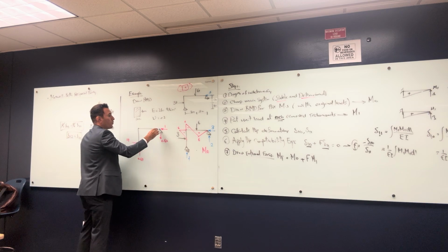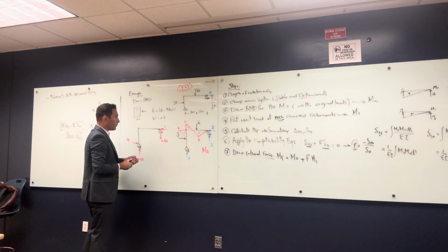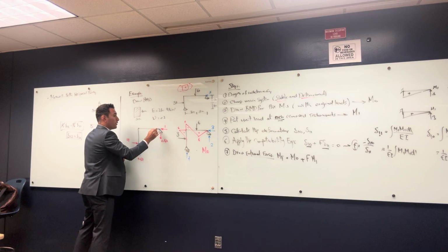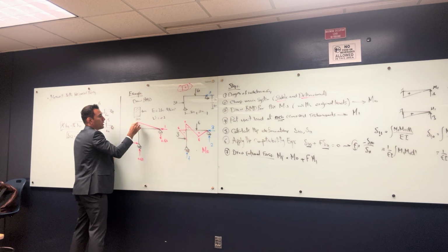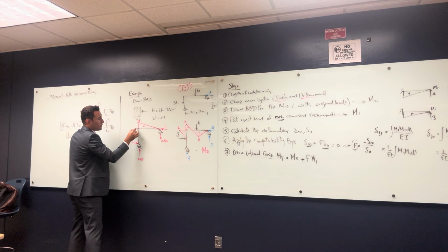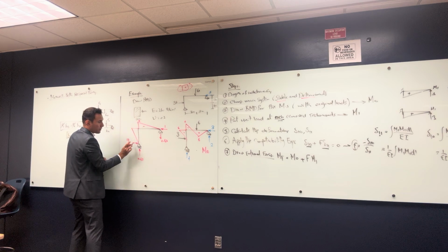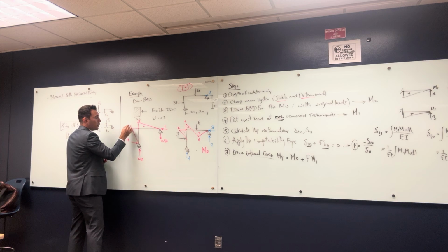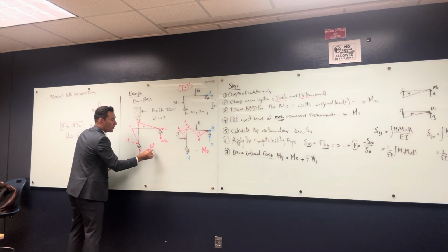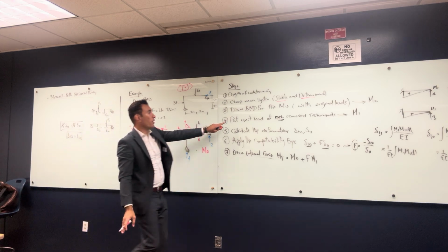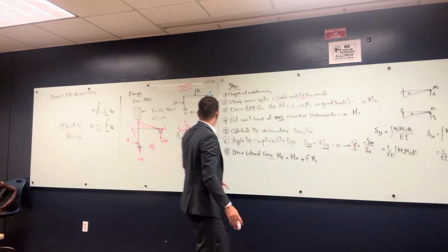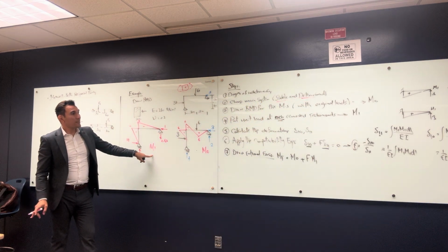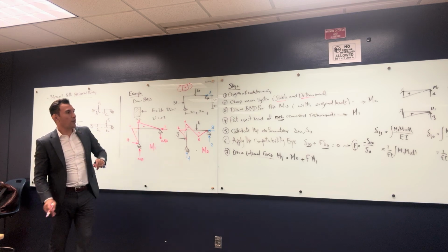So we're going to have 0, and then I'm going to connect it by -4 because this bending moment is that way. This is negative and this is 4. Same thing, you'll find this is 4 because it's 1 multiplied by 4, and this is negative. I drew M1. I did step number 4, put a unit load at each removed redundant and find M1. Okay, what is the next step? Calculate the deformations, delta 1O and delta 1-1.